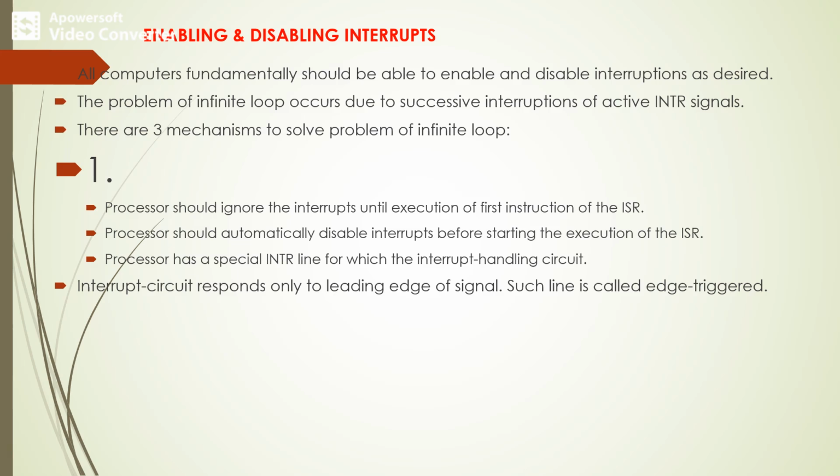Consider the case of a single interrupt request from one device. The device keeps the interrupt request signal activated until it is informed that the processor has accepted its request. If this activated signal is not deactivated, that may lead to successive interruptions, causing the system to enter into an infinite loop. For example,